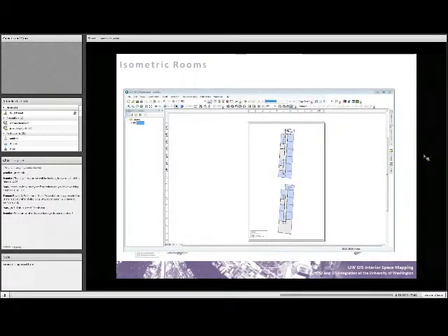There's also going to be a Python version of calculating the world file rotation, so you can actually go in through a toolbox and then select the world file, and it'll just print to the screen what the rotation is. We actually are using the Python tool in a more complex way to directly update our feature class that stores the rotations. So it'll actually read the folder that's containing the world file, which has our building number as the first 4 characters, and it'll use that to find the building in the database table and then update the rotation directly.